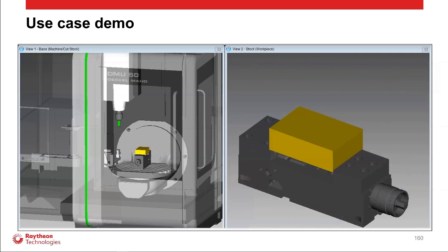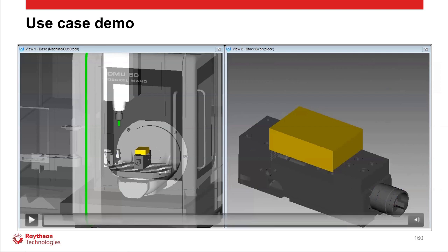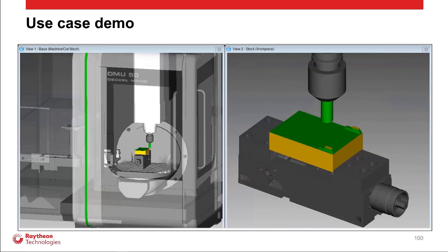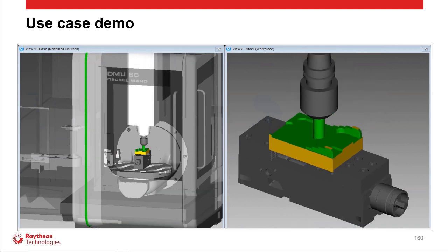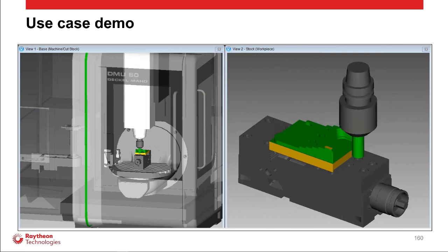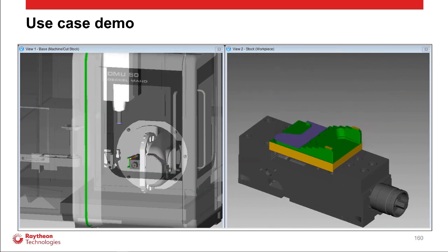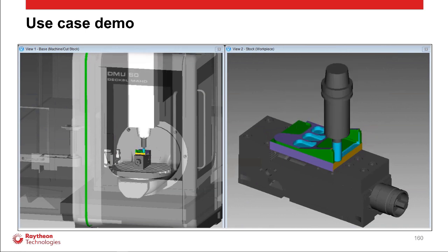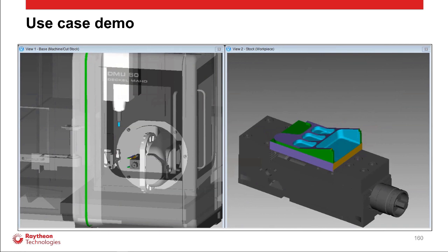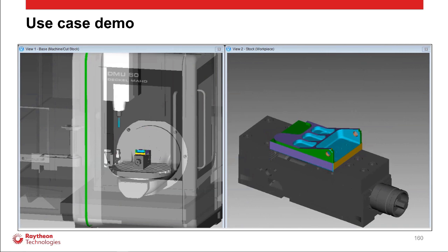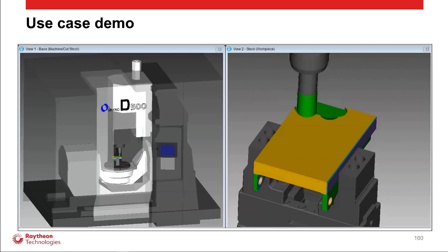And here is the video that shows how it works basically. So this is more or less the digital model of how the machine will behave during this cutting. For background, we use our physics-based model to predict. Per motion step, once the tool moves and contacts the workpiece, we simulate the forces applied on the tool side and also on the machine side. And we can also predict the spindle load and the power consumption.